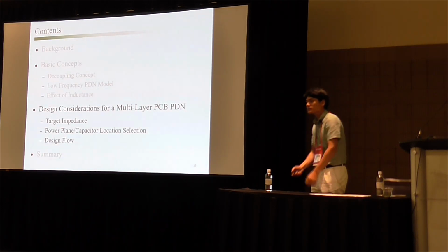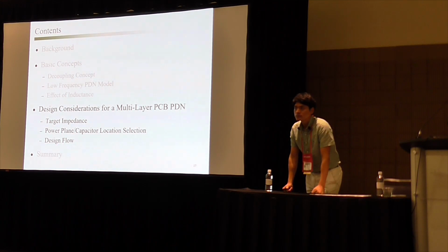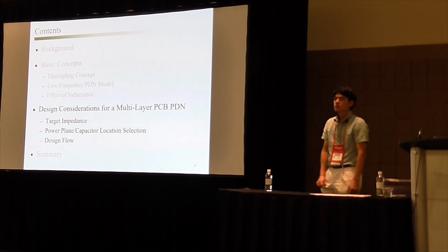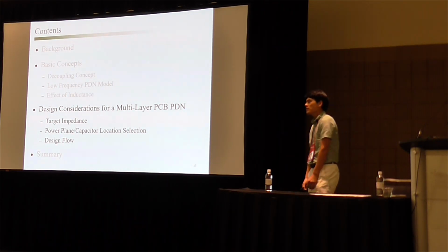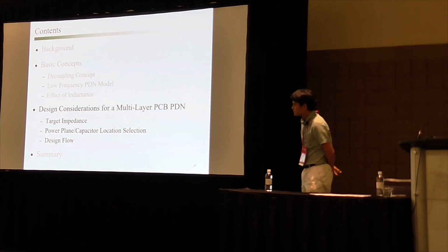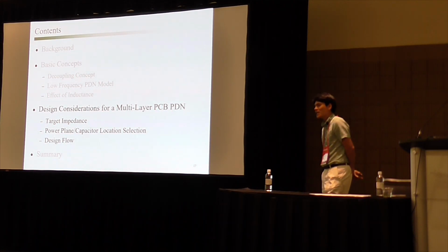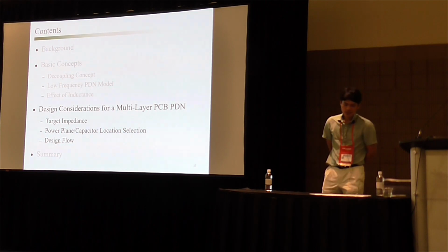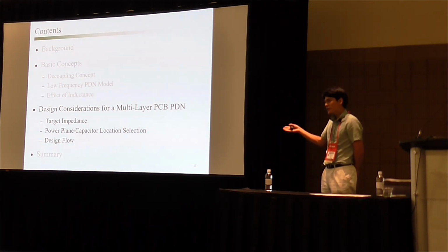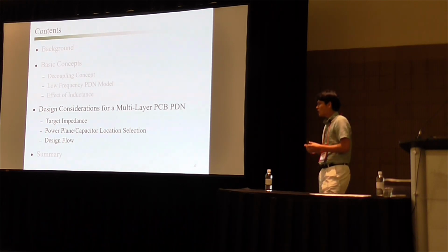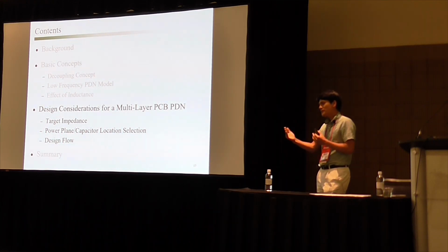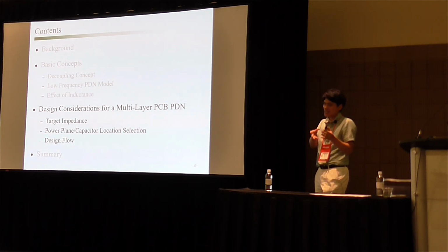What about the delays that are induced by these decoupling capacitors? If you put a lot of decoupling capacitors, there should be a lot more delays. So you're talking about the delay. This is the frequency concept. You might get confused about this, but usually for higher frequencies, we put the decap very close to the IC.